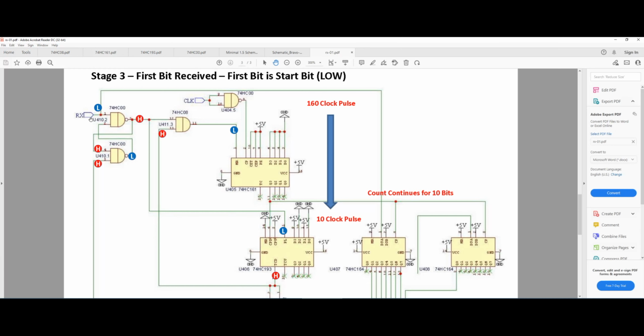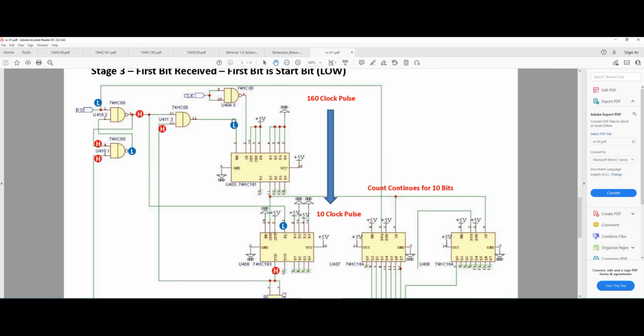When this line goes low, it immediately puts a high on the output, and now we are in business, right? Because we had that signal previously latched to high, and with the arrival of the first bit, we set that output to high. So this AND gate here will be outputting 1, which basically means that I think this is wrong here. This should actually be high. I'm sorry about that. So imagine that this is a high signal, not low. So high comes in, and now we have a high signal on the master reset.